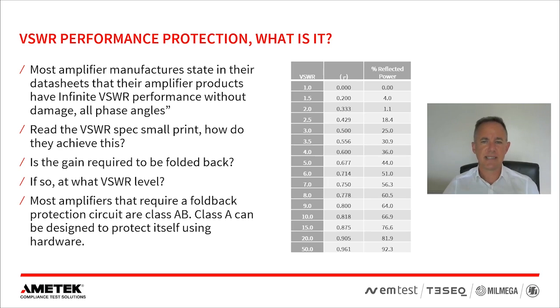A misconnection is a common cause for this type of damage, where the signal is switched on, the amplifier is presented with what effectively amounts to an open or short circuit load condition, and doesn't have time to react to this condition, allowing power through its protection and damaging the internal RF transistors.